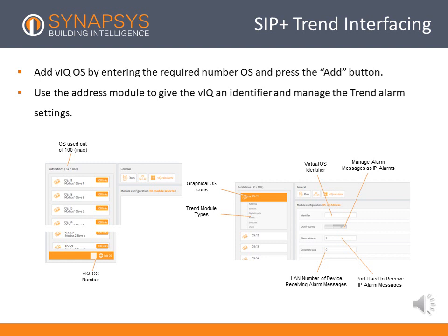Open the outstation and add a label, alarm, specifications, and attributes that may be required. The next 4 headings will enable individual configuration of sensors, knobs, inputs, and switches. The final option defines the users for the outstation, allowing trend security to be added.